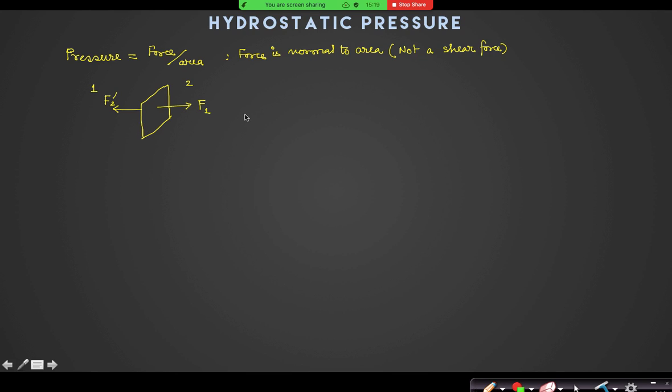So if there is an air and water interface, then you can find the force at any point if I know the pressure. Just multiply it by the area, and I will find the force. Remember that force is always perpendicular to the surface. But pressure, if I ask you what is the direction of pressure, does it have any direction? Pressure at this point, what is the pressure?